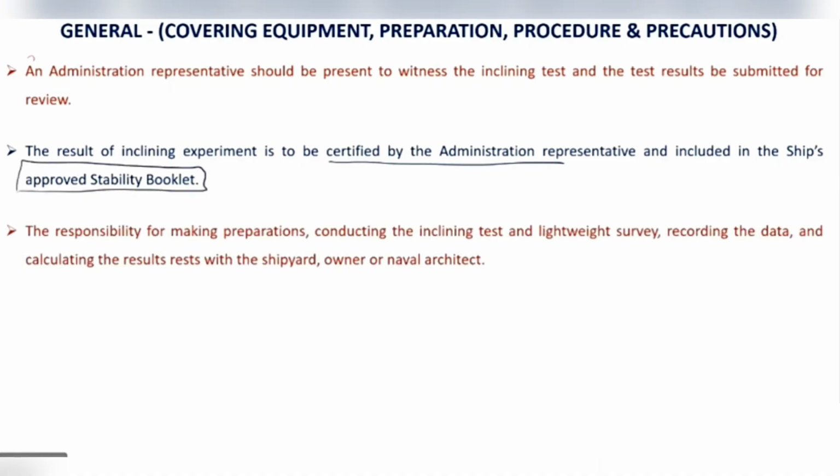Responsibility for making the preparations, conducting the inclining test and lightweight survey, recording the data and calculating the results rests with the owner or the shipyard on the owner's behalf, not on the fleet. Flag state will witness, review and certify.